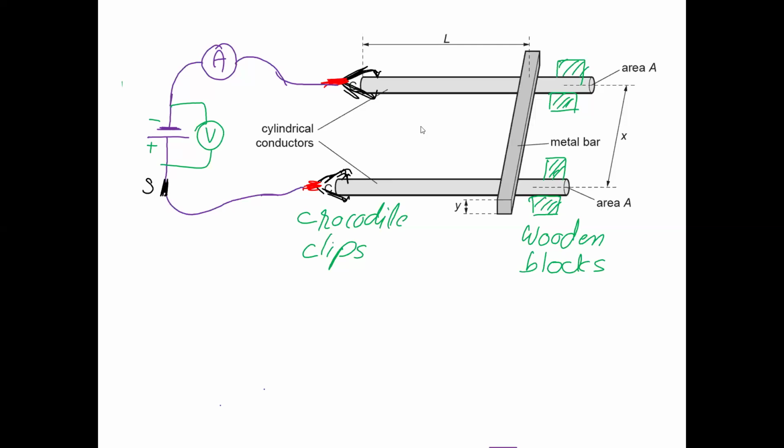Connect the ammeter in series, voltmeter in parallel. Make sure the connections are tight and dry. No moisture or water should be there.